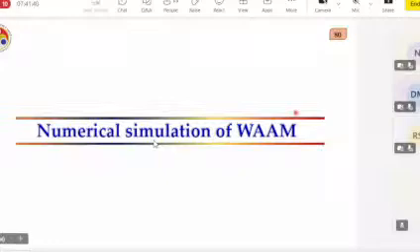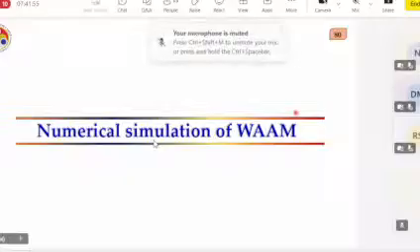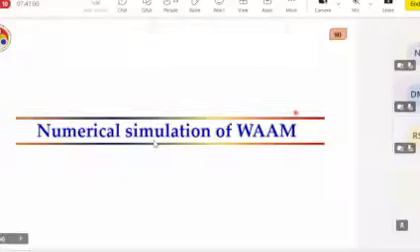And finally, we need to apply the thermal loading at the bead center point. To apply the thermal load, we need to use a subroutine, DFLUX. So this is a thermal loading condition. Basically, we consider the heat source to be a double ellipsoid.